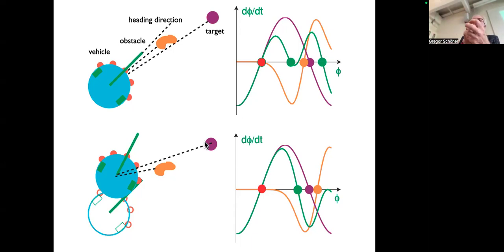I mean, the attractors move, and it would be tracking these attractors with the relaxation time, how steep the dynamics is, and that has to be something that is tuned also to the control, so that you can actually achieve that in control. So it has to all be adjusted correctly. On our robots in practice, it was often the numerics that was the limit, that we had to get the sensor information in time. And therefore, you can't really tolerate changes of the dynamics that are too fast. Then you're not in the attractor. And that meant that we had to put a speed limit on our robots. Some of our robots would actually be able to move much faster, but because of the sensor information in our implementation, we needed to go somewhat slow so that it could actually do the computation.